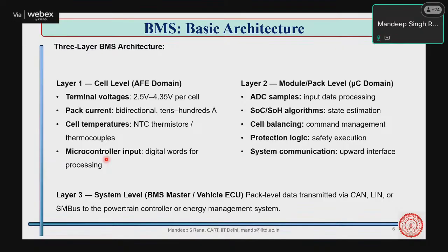Now, if you look at this particular side, which is the AFE card or unit, this is the unit which is being shown over here. These are the small cards which I was talking about. They are called analog front end units. Sometimes some people also call them active front end units, but usually the more common or more accepted terminology is analog front end unit. It has various responsibilities, including sensing, filtering, protection features, relay features, and communication of the data, and some small data management as well.